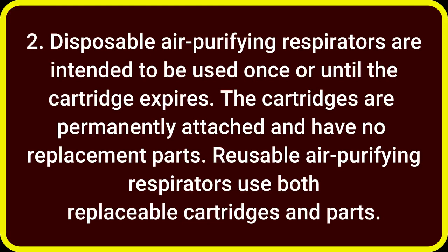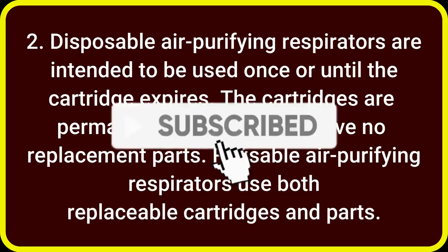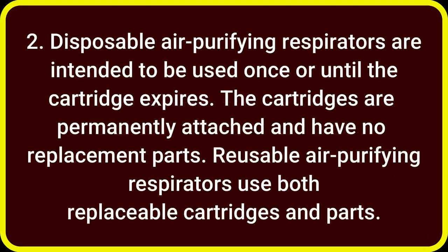Here you need to note down that the replaceable cartridges and parts must be from the same manufacturer to retain NIOSH approval. Disposable or reusable air purifying respirators have no replaceable parts except cartridges.